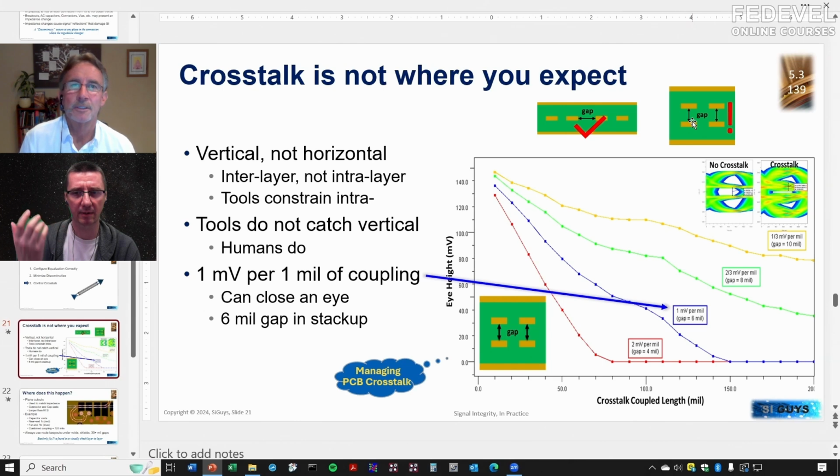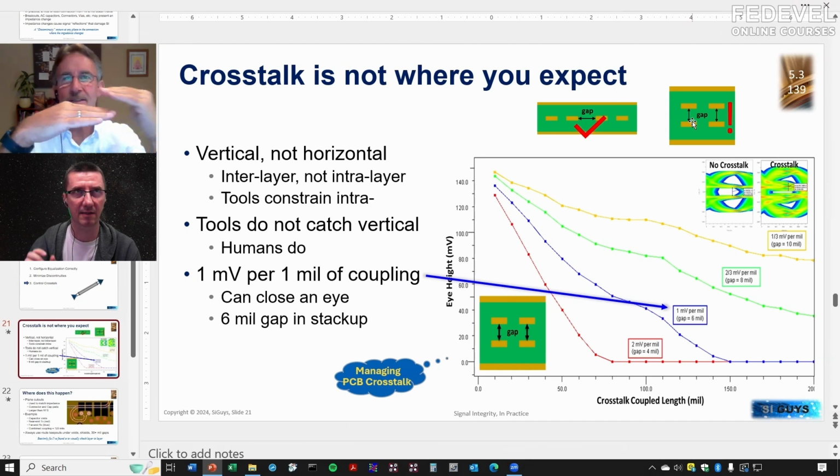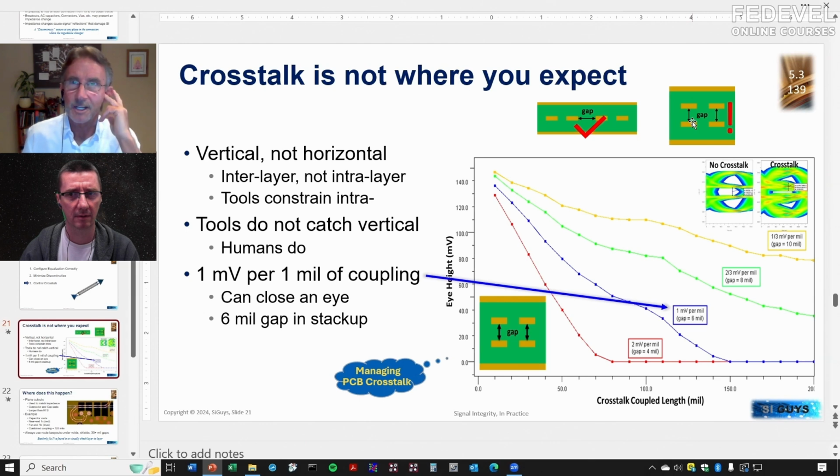The dielectric can be very thin. Yeah, it would be common in the boards I'm working with to have the prepreg or the core, the dielectric, at 3 mils, right? Yeah, exactly. Three mils, then that's your plane. 75 micrometers, I think, if I'm right. Micrometers. This is great, we got Europe and US talking right here. I still think in mils.